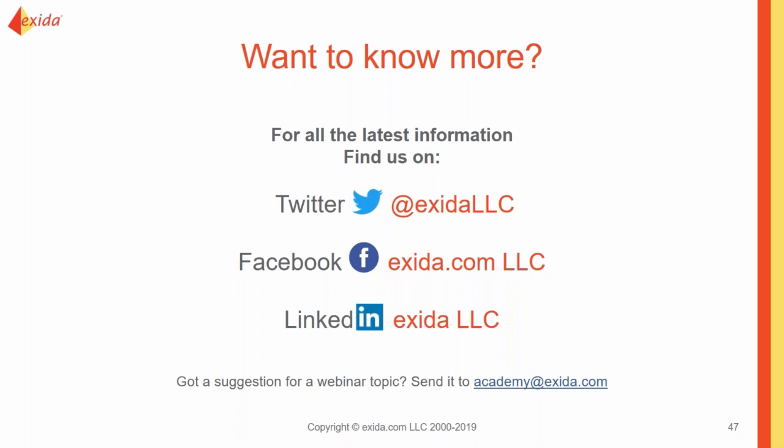Oh, some more came in, so hold on. We have a question about mixing and matching Route 2H and 1H devices within a CIF. No, right now you cannot be mixing Route 2H and Route 1H devices. You need to evaluate the entire CIF per Route 2H or the entire CIF for the safe failure fraction, or the entire CIF for both.